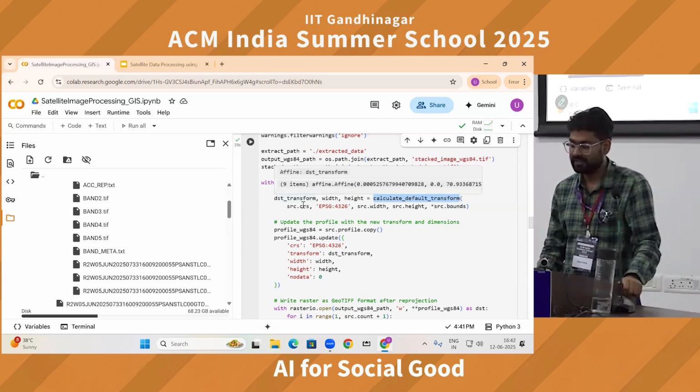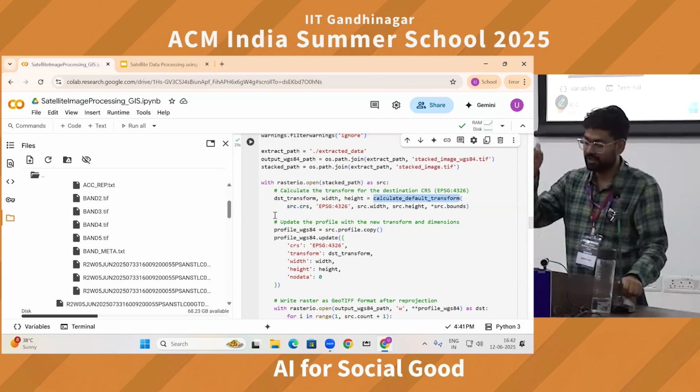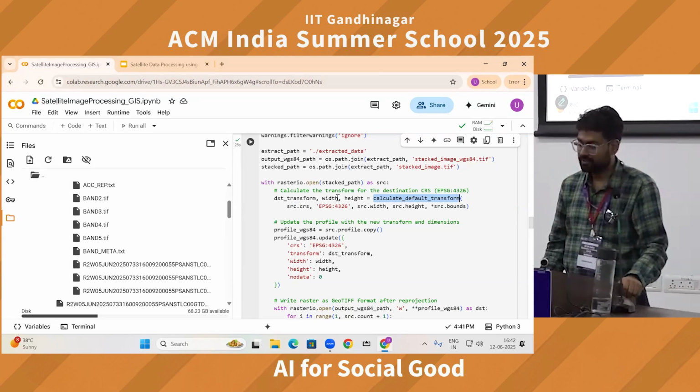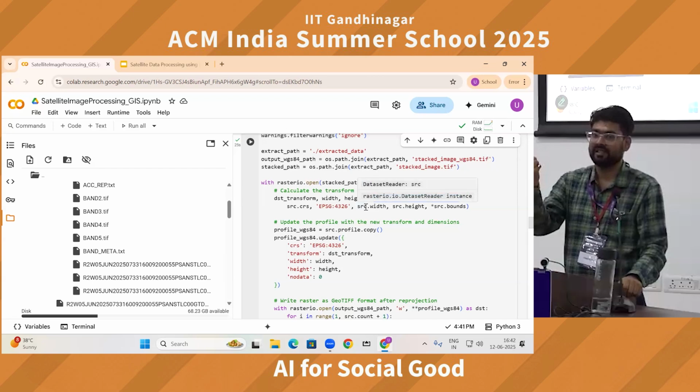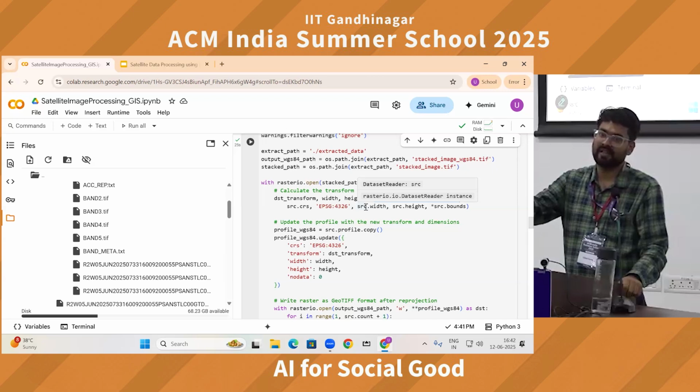The destination transform holds the values of the corner coordinates in EPSG 4326. And because of the change in projection, the pixel size in the X direction and Y direction may change.